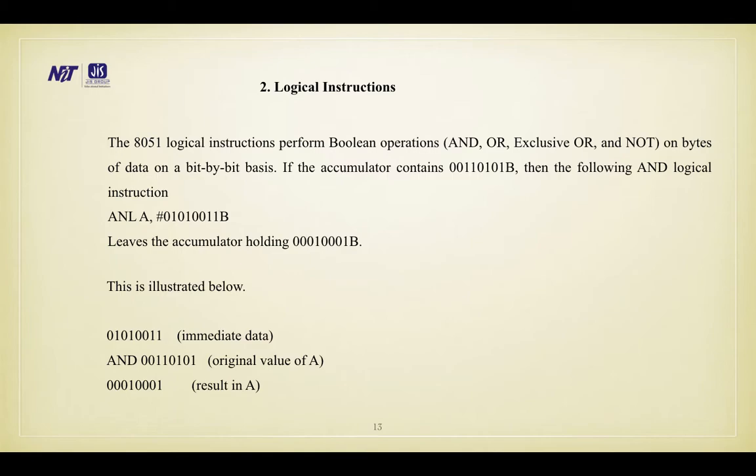01010011, immediate data, AND 00110101, original value of A, gives 00010001, result in A after the ANDing operation.